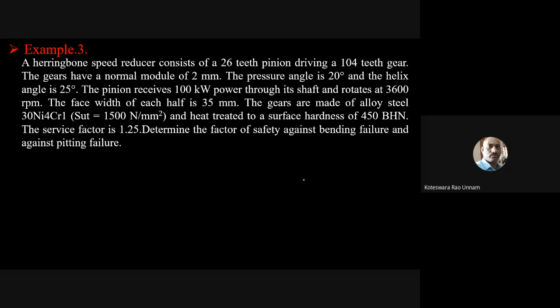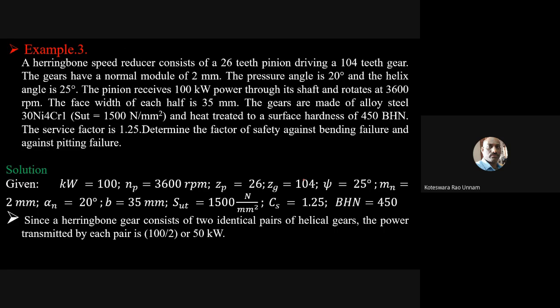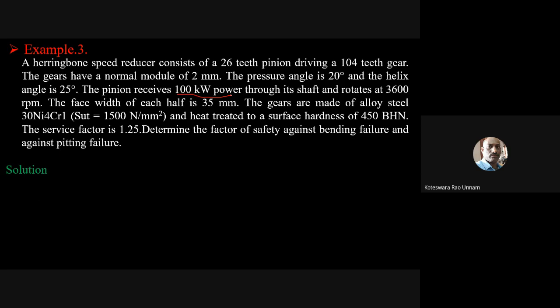Of course, the solution is similar to your helical gear only. Here the only thing you need to do is, he has given the power as 100 kilowatts, but you need to design for the single gear for 50 kilowatts. That is the only difference. Anyway, note it down, then we'll discuss the solution.